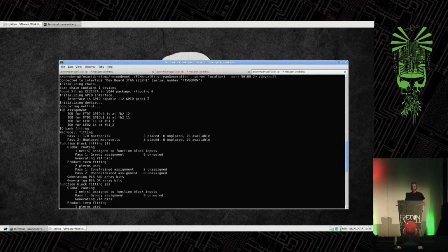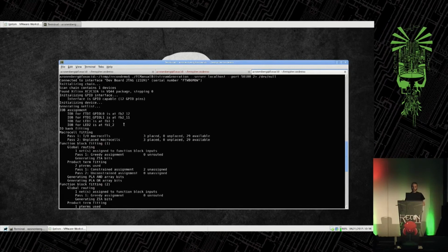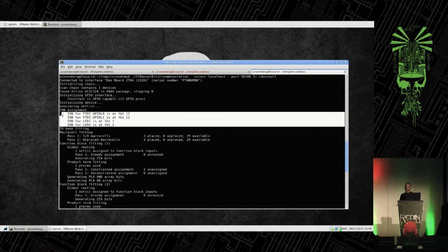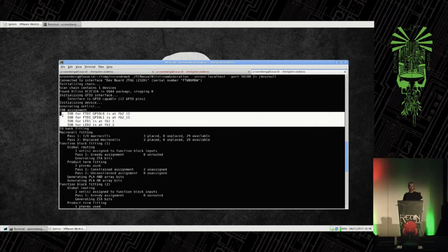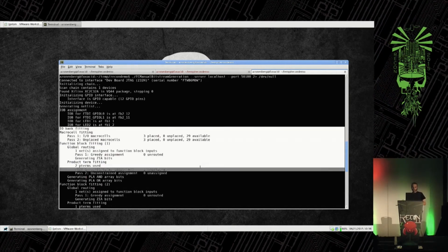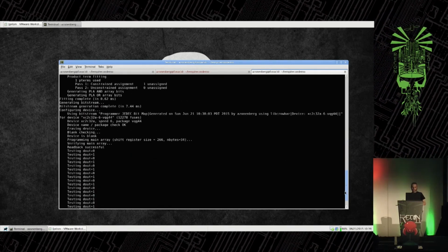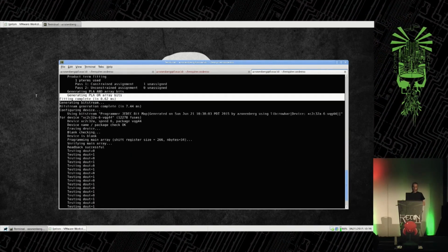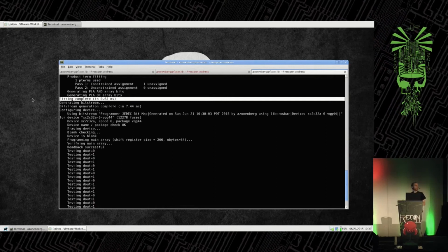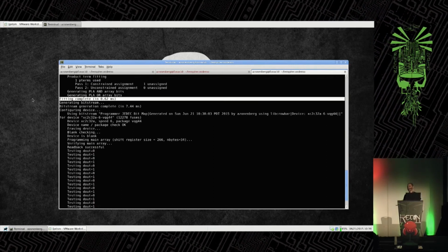Anyway, so we confirm, okay, yes, the FTDI chip has GPIOs on it. We generate our netlist. We figure out the actual function block and macrocell locations of the I/O buffers we're using. Then it runs the fitter through I/O banks, macrocells, function blocks, does global routing, repeats for the other function block, does global routing for that, confirms, okay, fitting is complete. Took 620 microseconds. If any of you have used the Xilinx compilers, they're not that fast.